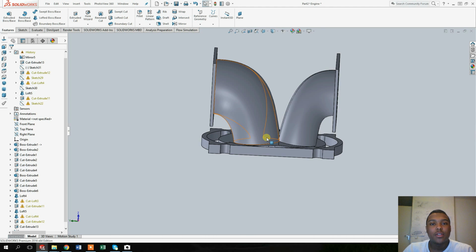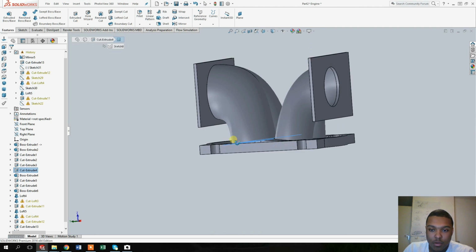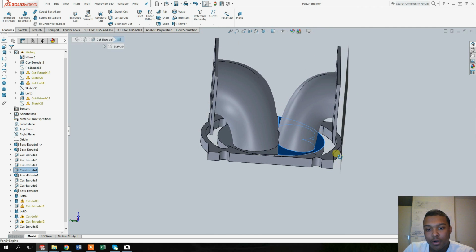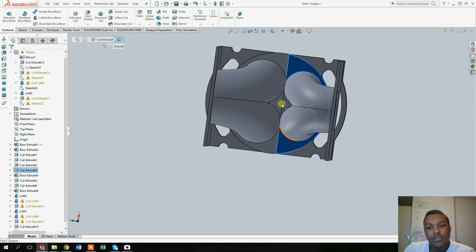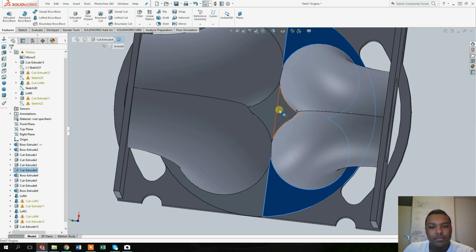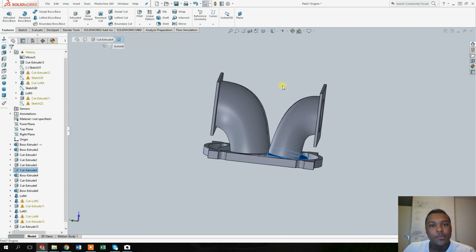So the last thing I want to discuss in this episode is that not only do I use the free valve technology, I also wanted to combine it with two spark plugs, so that we have a spark plug that comes in right here, and we also have a spark plug that comes in right here, and direct fuel injection that would come in the center of the cylinder, not quite the center of the center, but somewhere around here. And with this technology, we could use cylinder deactivation.